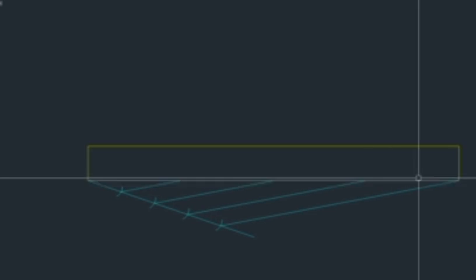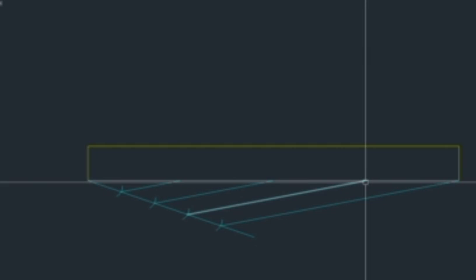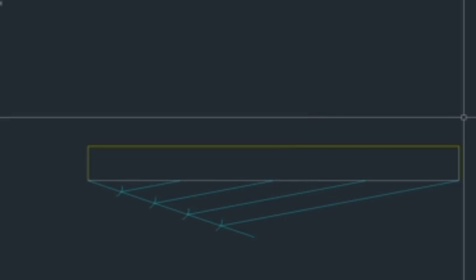Keeping your set square parallel to this, moving it, you draw parallel lines, or using your mini drafter, you draw the parallel lines. Now you have divided this, so the entire length will be divided into 4 segments of 4 centimeter each. Now you project this length. This is over.